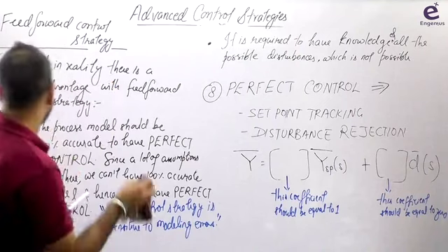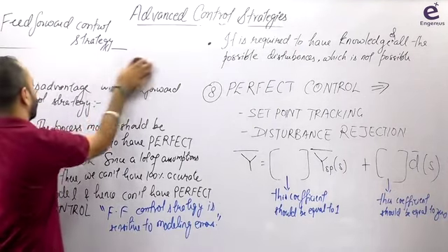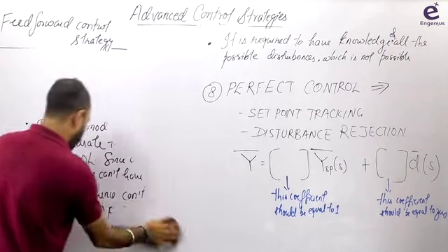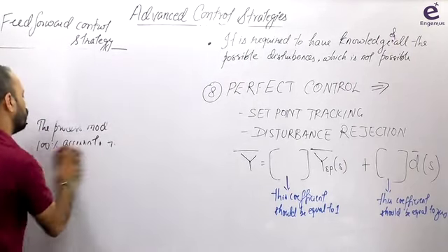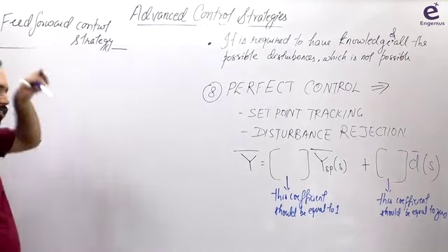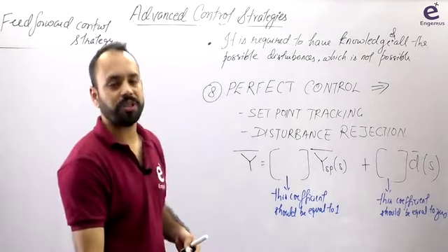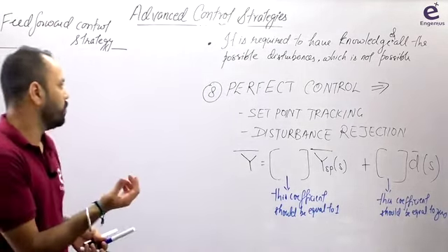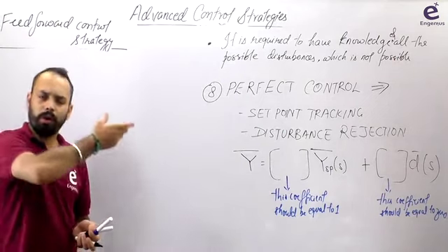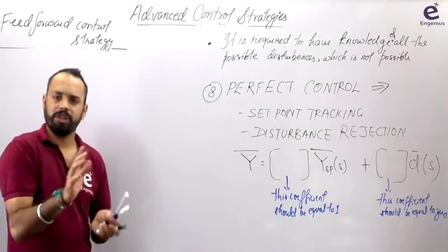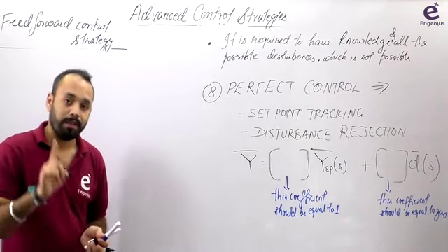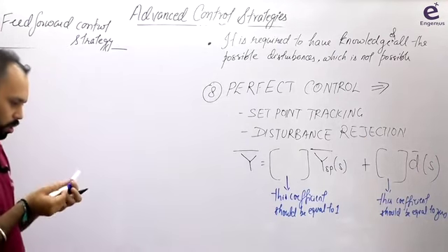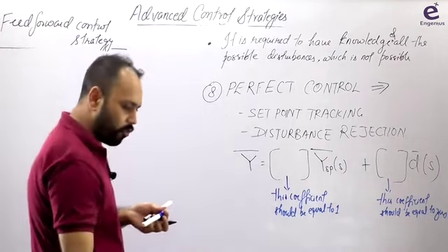Now, let us make a feed forward control block diagram. It is not very typical, and you can make it easily. But let me tell you that feed forward is a totally new kind of control strategy. Whatever shortcut method we have learned, forward path divided by 1 plus open loop transfer function, is not valid here. But the basics of block diagram are valid. So what is the block diagram for this feed forward control?